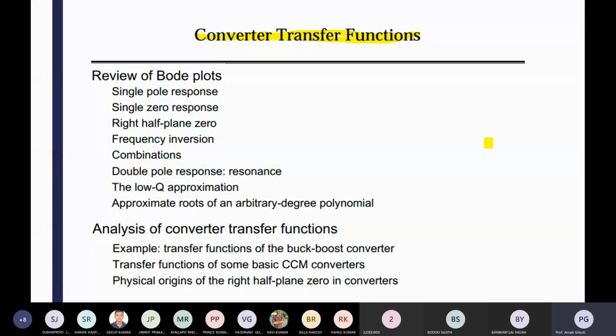Again, for minus 50% deviation, 12 minus 6 volt, you suddenly reduce the reference voltage from 12 volt to 6 volt, and you need to check what your converter output is. If it comes exactly near 6 volt, you can say your converter is working perfectly in closed loop condition. That is called robustness study, that is, how robust your system is.